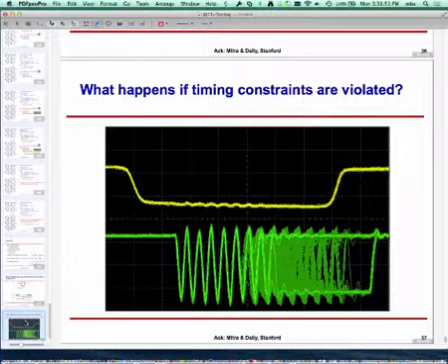Some setup or hold time was violated, and if you were to put an oscilloscope on it, an instrument to look at electrical waveforms for those who have never seen it, you would see that the output is just kind of oscillating. In metastability, if you monitor the output voltage, it goes into some realm where it is neither 0 nor 1, sitting somewhere in the middle, and it can spend a lot of time there. And when metastability failures happen, essentially your computer crashes.